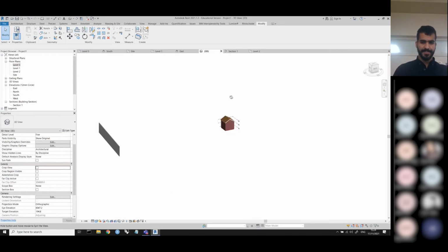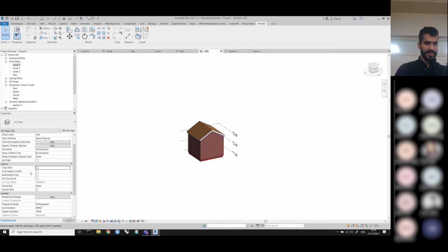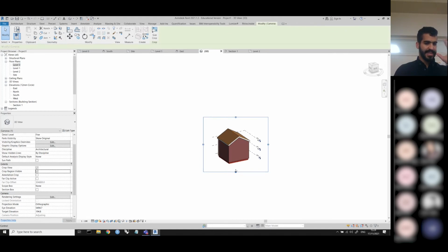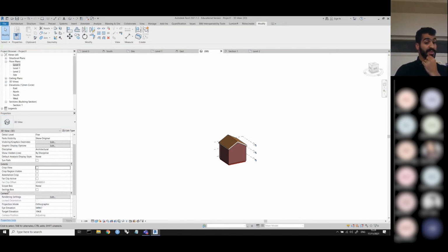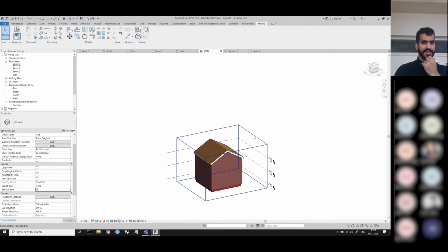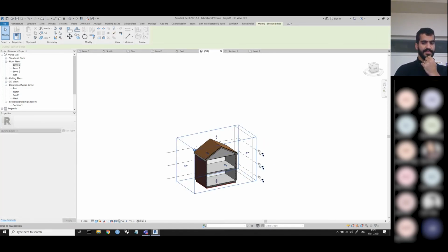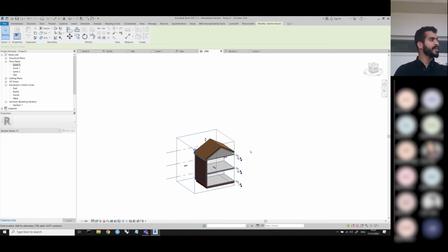So here, I'm going to delete this because it's pointless. I go in here. Extent. This is my extent view. That's fine because this is my default 3D view. I just want to leave it open. But there's something here that's very useful for you for perspective sections called the section box. So if I tick on that, apply, it gives me this box. And with this box, I can do a 3D section in different ways, right?